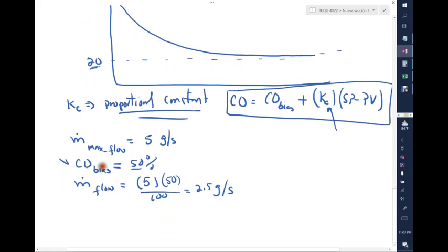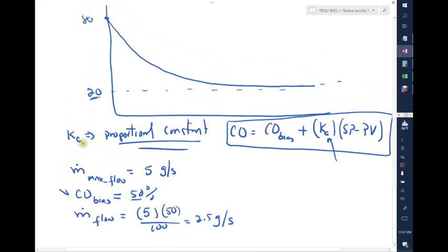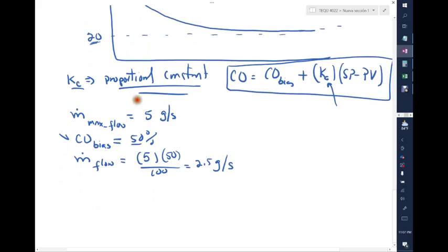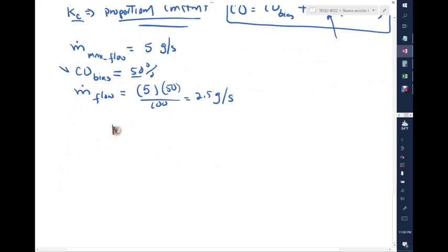Now, from this type of curve, in order to calculate Kc, I need 2 important parameters. Let's talk about them. For example, Kc is basically 1 over a value that is known as Kp times the time of 63% change in the curve divided by the time of 28% change in the curve, and all that elevated to 1.22. So that's the equation that I'm going to be using for my calculation of Kc. So the question is, what is Kp?